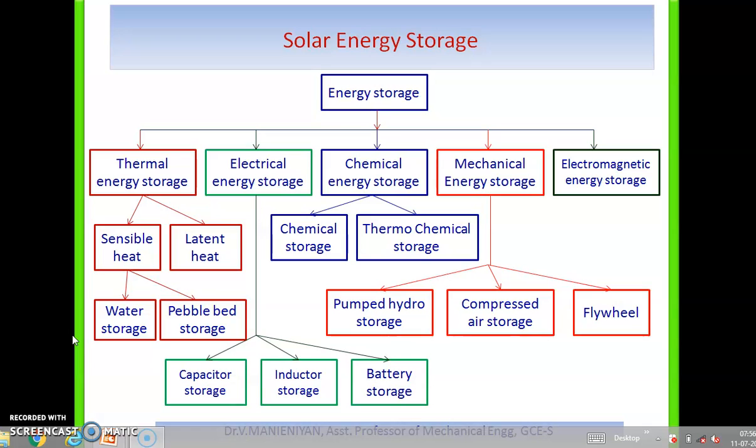For heating, energy storage as sensible heat stored in water is logical. If air is heated in a collector, storage as a sensible or latent heat effect in a storage unit is needed. In such a case, sensible heat is stored in packed bed heat exchangers. If photovoltaic or photochemical processes are used, storage is in the form of chemical energy or energy stored in batteries. So such energy may be stored in a variety of forms as needed: heat, electrical, chemical, mechanical or magnetic energy.